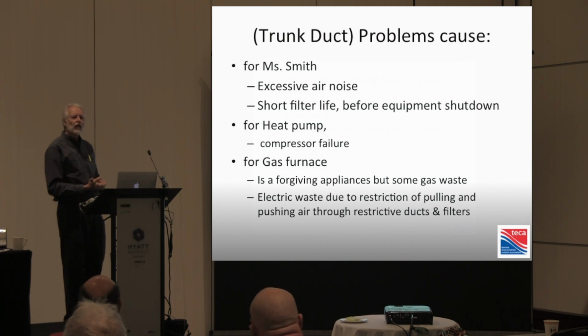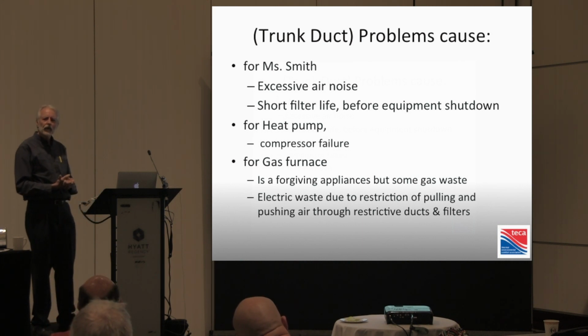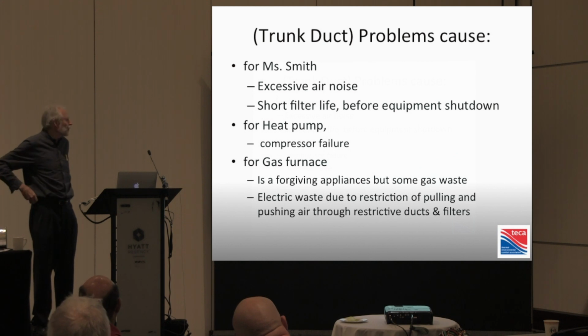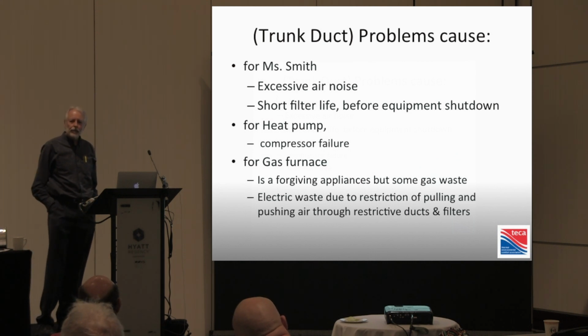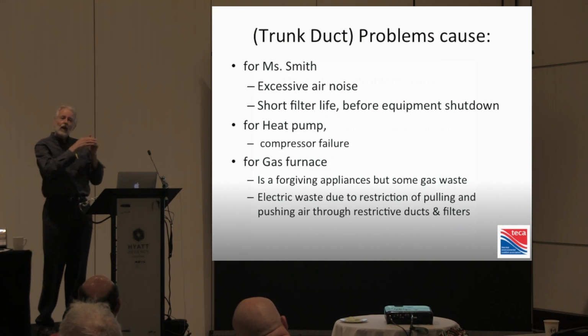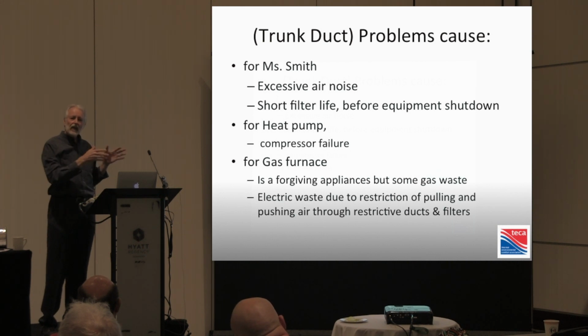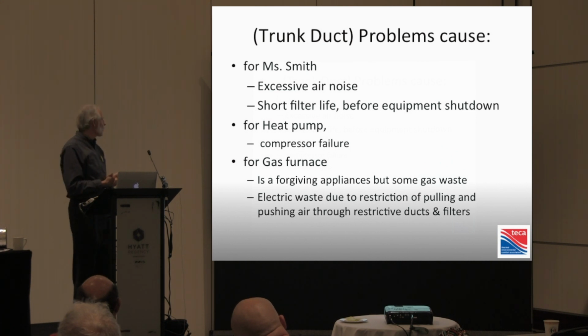Gas furnaces, on the other hand, are very, very forgiving. You wouldn't believe the abuse that you can give a gas furnace and it won't fail. Amazingly forgiving appliance. But you will pay for it with gas waste. You will pay for it with a shorter venter life, because the venter is ventilating the exhaust products out to the outside. If you're not taking heat off in the furnace, where is it going to go? It's going out through the vent system, and your venter motor will have a shorter life for that reason.